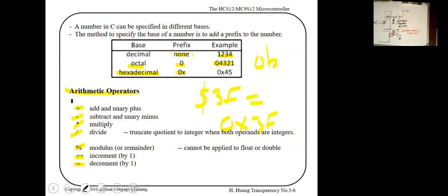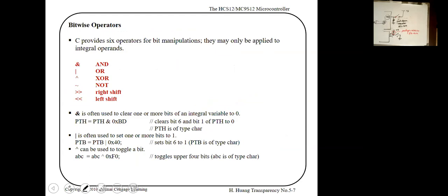Okay, so these are the set of operations that you already know. Bitwise operations are very, very important when programming microcontrollers in general, because through bitwise operations, you can perform operations between a value and a mask, which is very essential, as we saw in configuring the ports and reading the ports. You need to perform bitwise operations, so you can do the same at the high level. This is the AND, OR, XOR, NOT, right shift, and left shift.